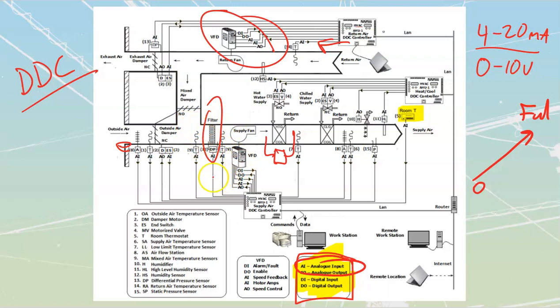And so I'm just going to set a range, and I'm going to say that when my pressure difference across there is more than this, I'm going to call for maintenance, so for a screen change or a screen clean or check or whatever it's going to be. Same with my coils, the actual hot water and cold water coils themselves. We will oftentimes see them over top of that. It's an easy way for us to electrically monitor the state of any sort of filtering, without having to go into optical recognition or anything crazy like that.